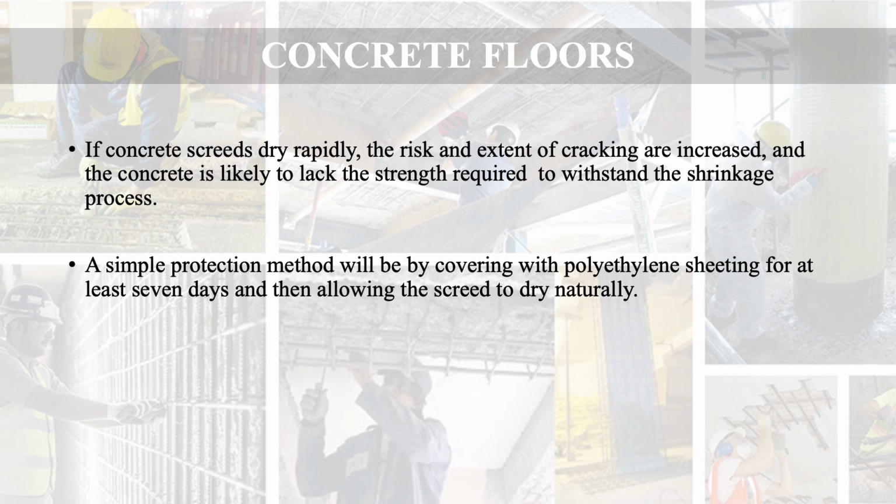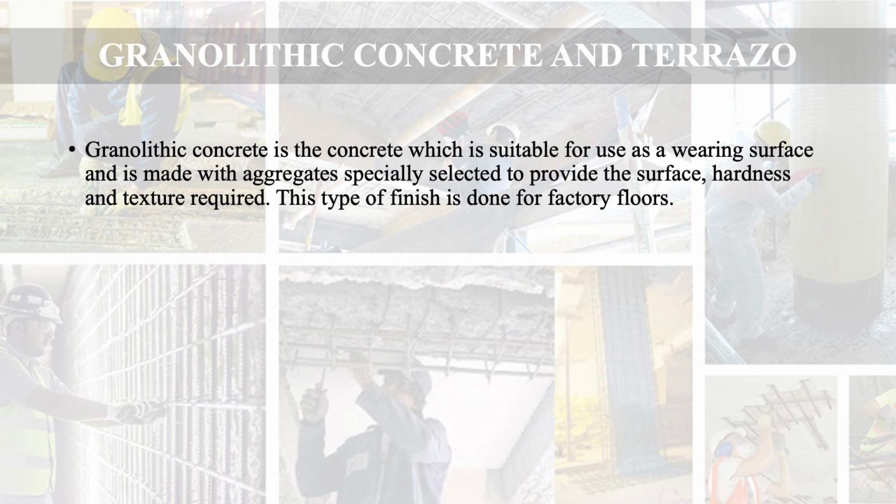A simple protection method is covering with polythene sheeting for at least 7 days and then allowing the screed to dry naturally. So that way you can increase the drying period. Now next we move to granolithic concrete and terrazzo.